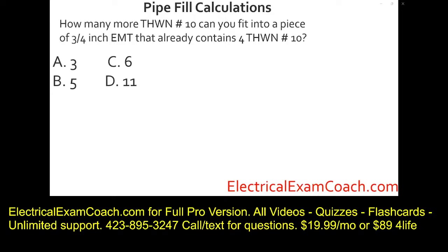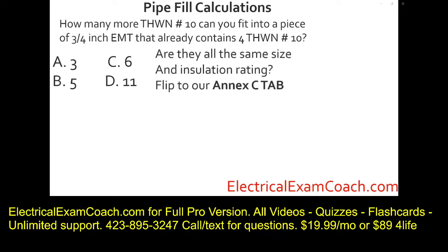How many more THWN number 10 can you fit into a piece of 3/4 inch EMT that already contains 4 THWN number 10s? The first thing we're going to ask ourselves, are they all of the same type and insulation? They sure are. So let's head to Annex C.